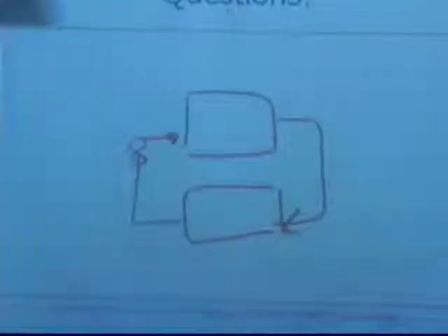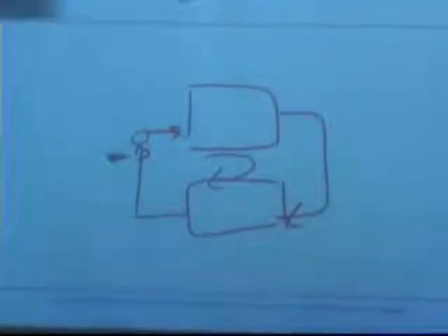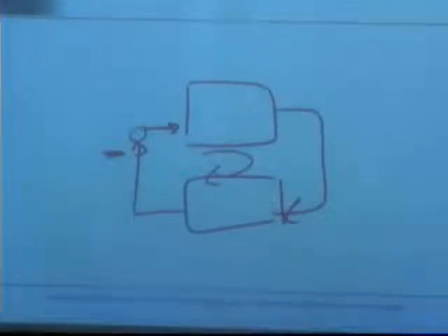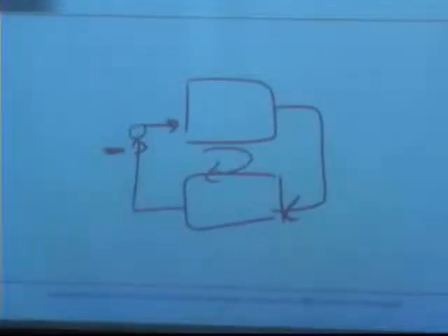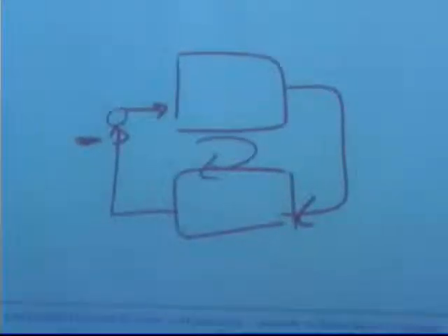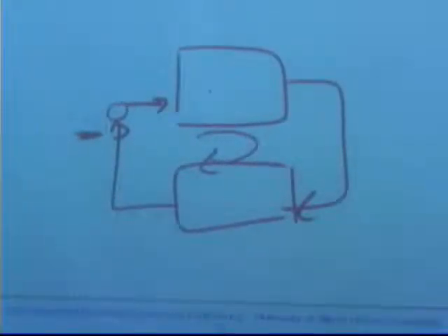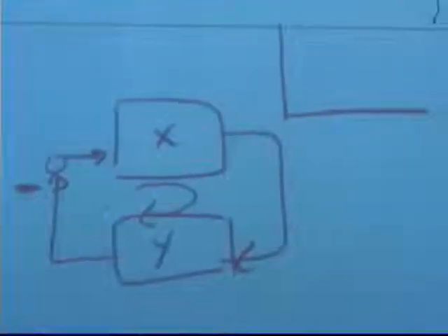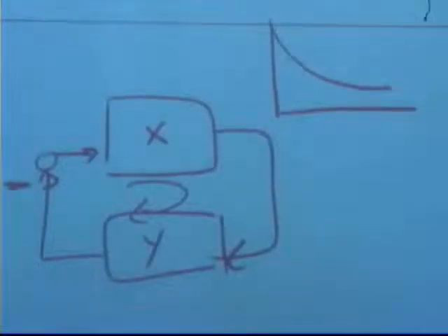If I bring information around this loop here, the information that comes back, I can put a particular sign on this piece of information that's coming back. So there's a negative, whatever the output was on here, the negative of the output of this gets fed into the input of this other system. And usually if you have negative feedback like that in engineered systems, that causes the overall system, let me pick some variable x that corresponds to this particular system, tends to be a nice stable system.